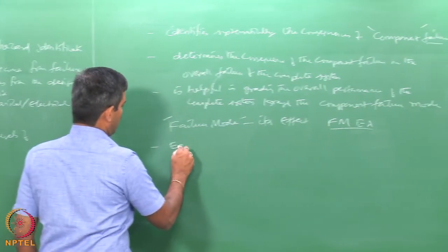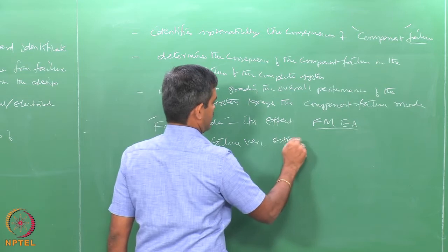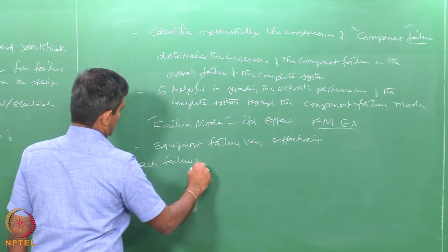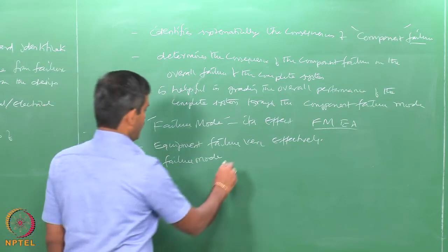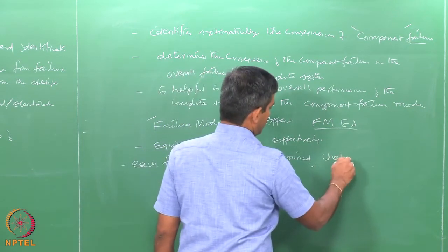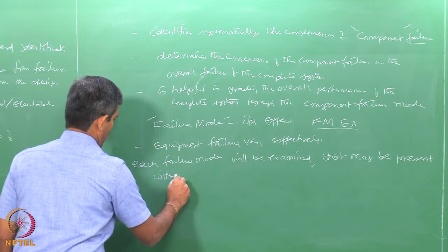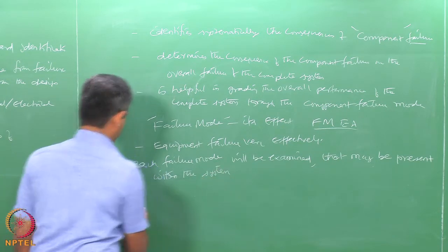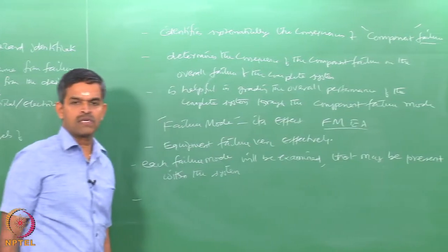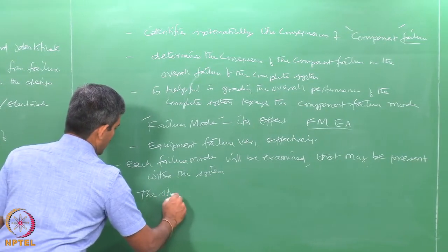This can identify equipment failure very effectively. In this study, each failure mode that may be present within the system will be examined. Then the effect of these failure modes on the overall performance of the system will be assessed. So, it will be done in stages, in sequence. The study is done in sequence,